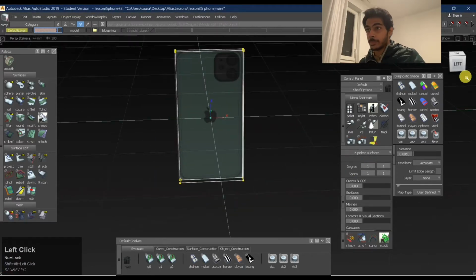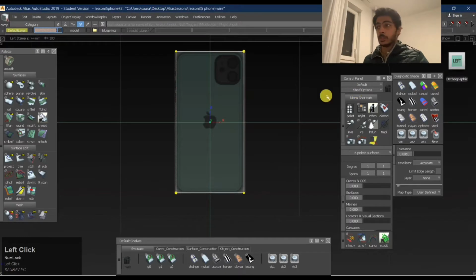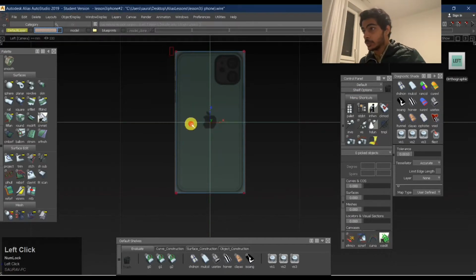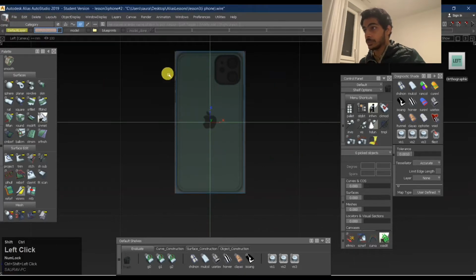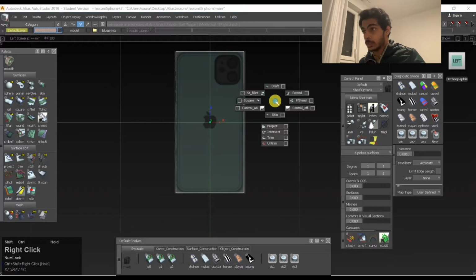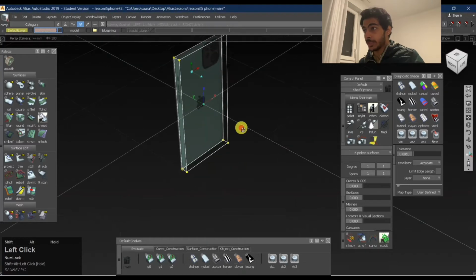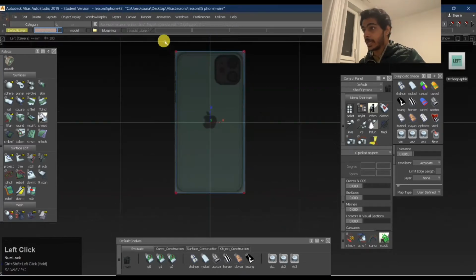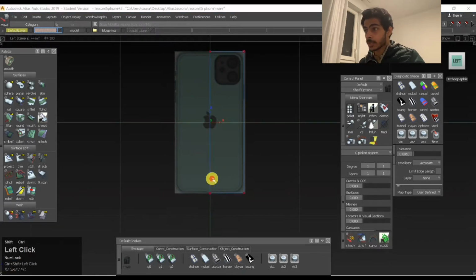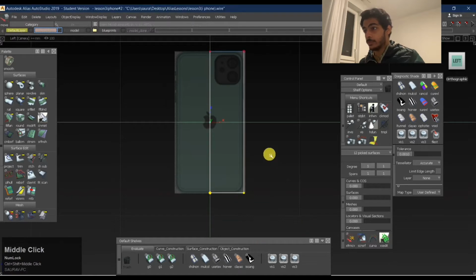we'll just make it into 1/4 of the whole grid, right? So we'll just pick these 2 points. We'll keep it as it was first. We'll just switch on the control points first. So Control Shift, left click, and it's Control on. So we switched on the control points. You see how there are these points. We just select these points and drag them to the edge of this grid, which is over here. We bring the CVs up as well. We bring them up over here.